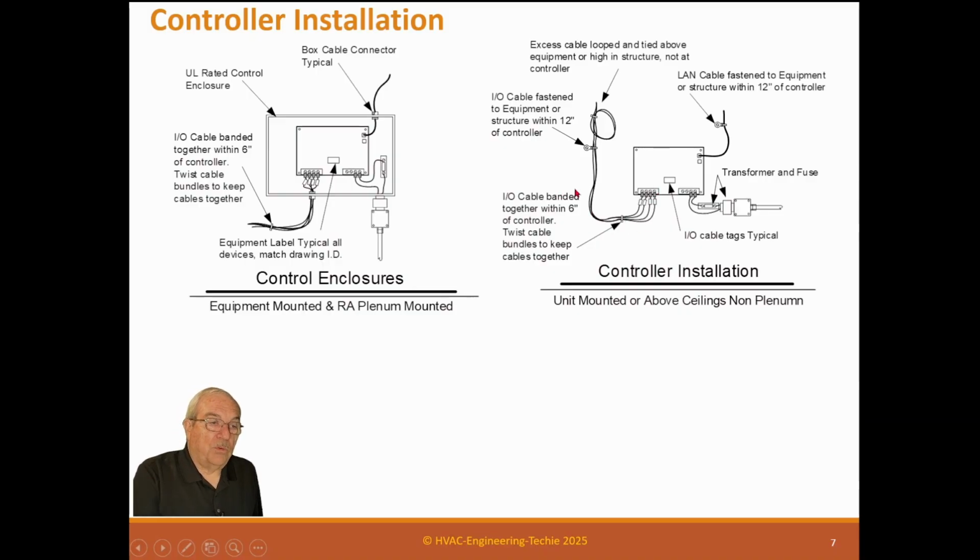Now, the one thing about wiring sensors, they should never have a connection. A temperature sensor or an analog sensor coming in should go completely from the end device completely to the controller connection. If you have to, you can bring it in to a termination board on the panel or a marshalling panel. But that's extra expense. We don't normally ever do that. But you should never ever have a field splice.